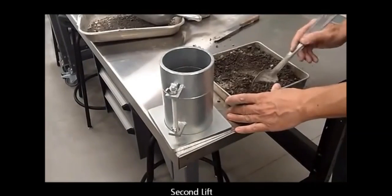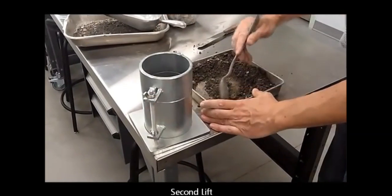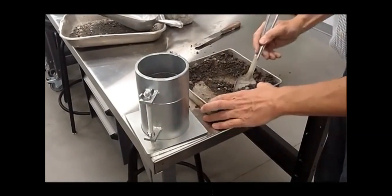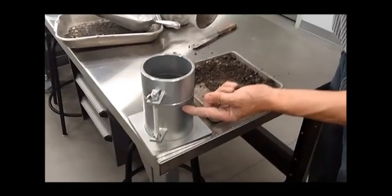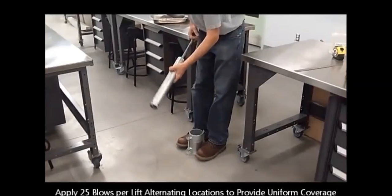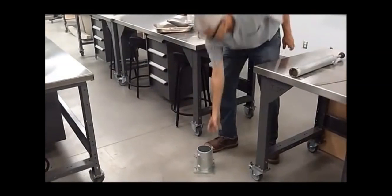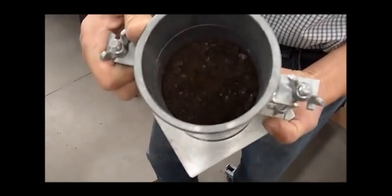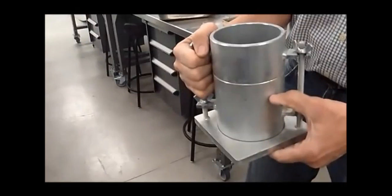Next, we'll take some more soil and fill it such that after compaction, it should approximately fill two-thirds of the mold. So again, we have filled the second layer. Now we'll compact the second layer using the rammer. Again, for the second layer, we are giving 25 blows, and all the 25 blows must be uniformly covered. So this is my second layer. It approximately fills two-thirds of the mold.